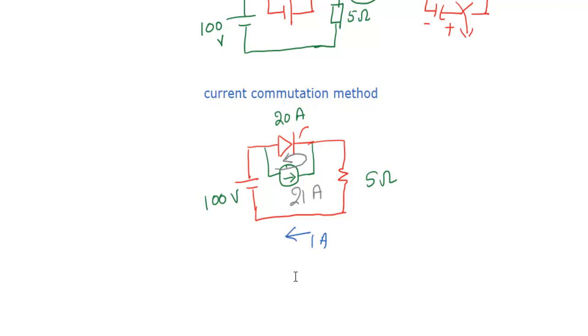So that means this thyristor won't conduct in the reverse direction. And whenever you change from positive to negative, the current has to cross zero. That means before coming to the negative current, this current will come to zero through the thyristor T. Then obviously this thyristor will be turned off at that time. So here we use the reverse current for the current commutation circuit. That's the meaning of that.